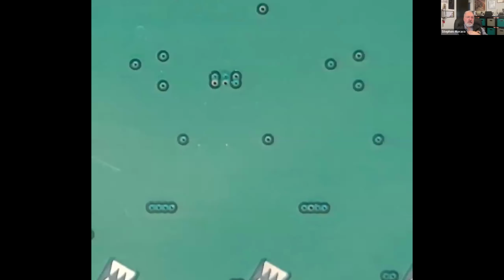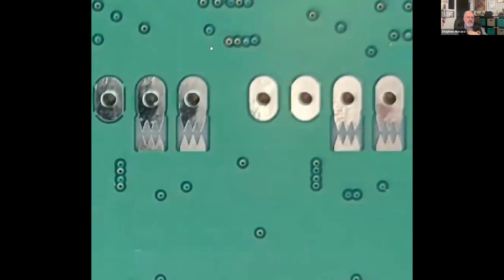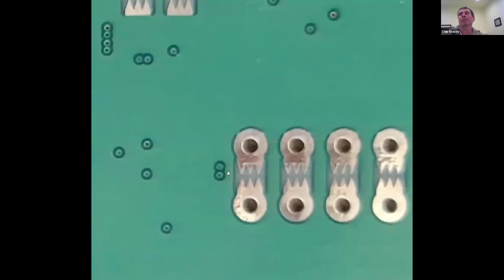So you're not putting little ghost icons on your board, huh? Those are really lightning protection. See, this is the ground plane, right? All this area is the ground plane. So some of the fingers attach to the ground plane and the other ones go to the pad that attaches to some external signal. In some cases, like here in the motors, half the connections are ground and half are signal. So we just do it like this.